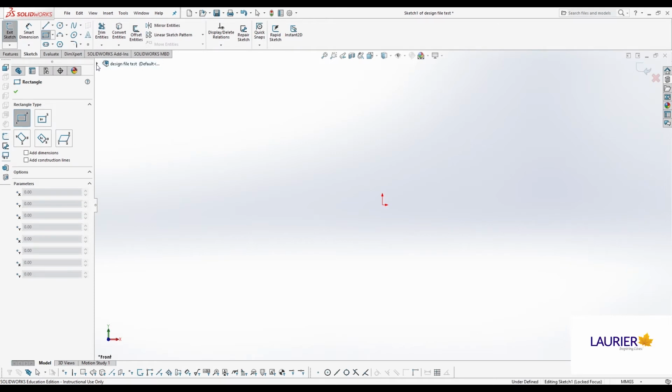So in this case, you can see you've got your rectangle type, and there's 5 different types of them, and it says 1, 2, 1, 2, 1, 2, 3, 1, 2, 3, 1, 2, 3. So those are your click points. Your first point is your 1, your second point is your 2. So to draw the rectangle, you click, release, move the mouse, and click again. The first click starts the shape, the second click completes the shape when it's a 2-point click shape.